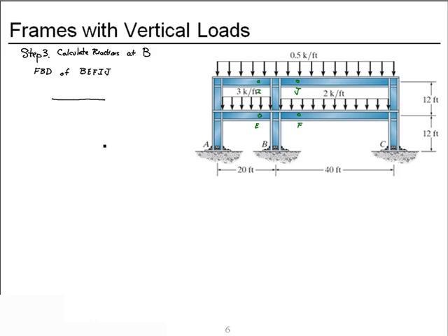So we draw our free body. With reaction By, Bx, moment about point B. We had the shear at E, which is a negative 24 kips, the normal at E, which is 0, a distributed load of 3 kips per foot over this piece,